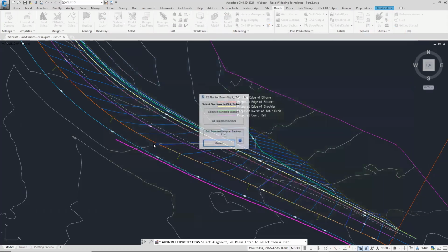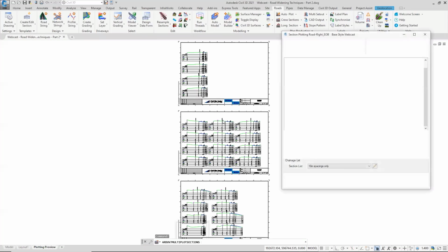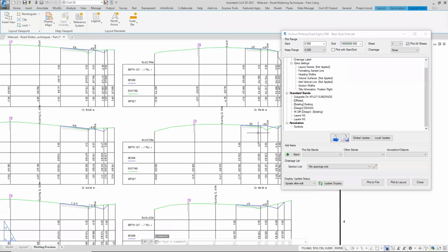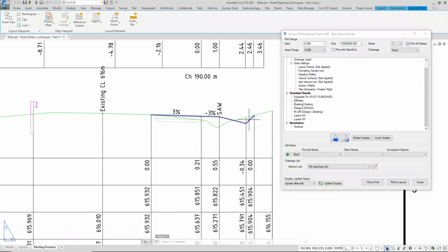You could tag any position of the road and then label that up. At the end of the day, if it's part of your template, then go and use the symbols option. If it's not part of your template and it's just a feature within your drawing somewhere, then go and tag it or use a layer.